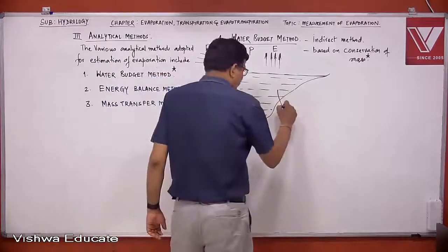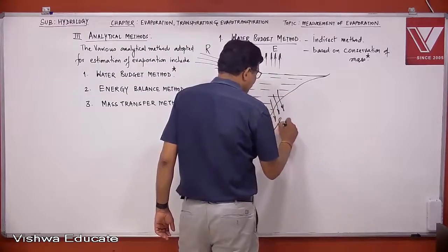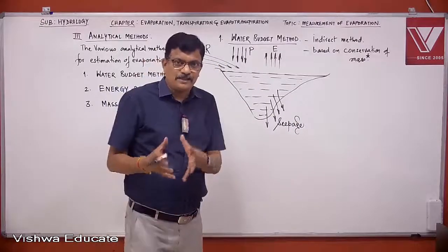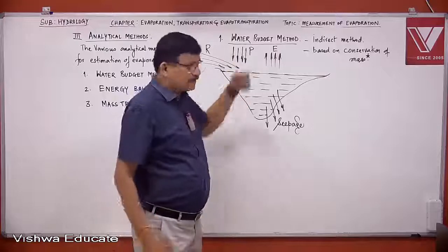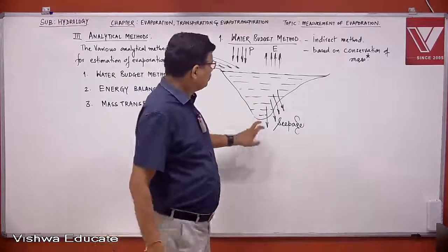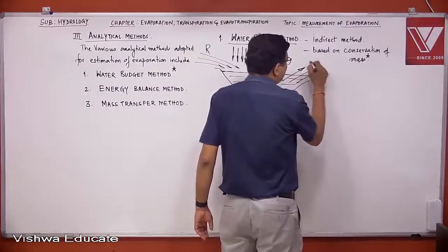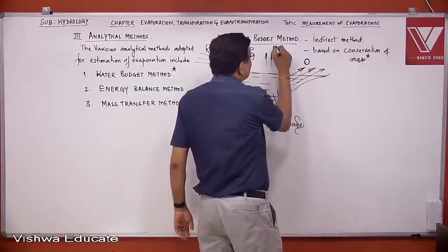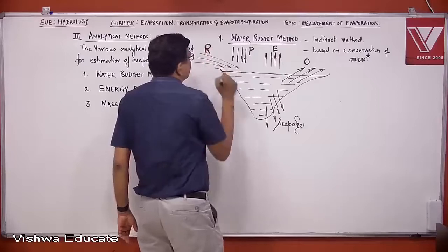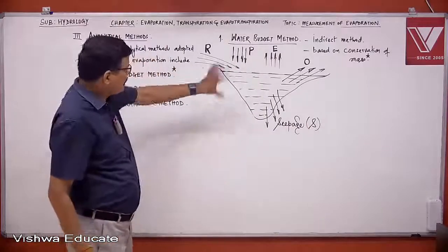Some of the waters will seep, so there is also a loss which I have not mentioned. Seepage is also a part of this water budgeting. This is also a major component to decide the change in storage of the reservoir. And then some of the waters are drawn for specific uses. This is the outflow, this is the evaporation, this is the precipitation, this is the runoff, and this becomes the seepage.